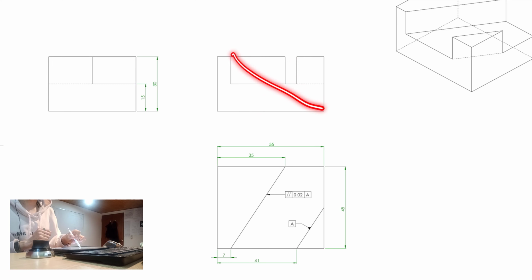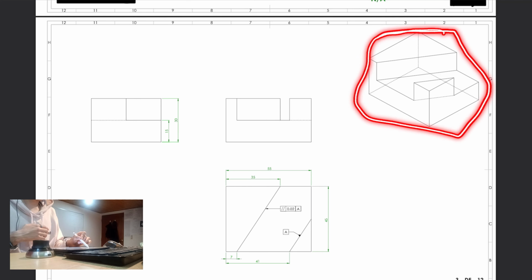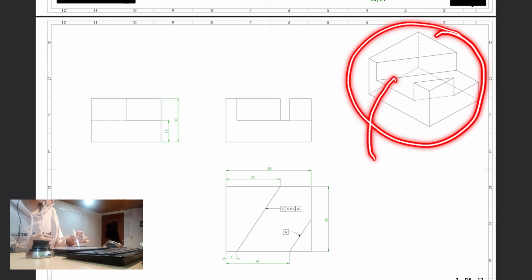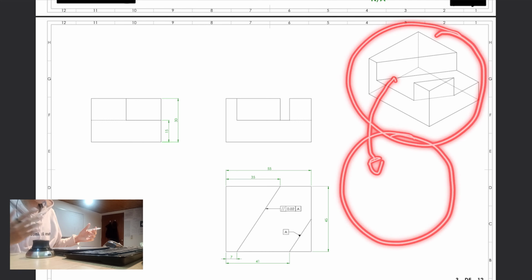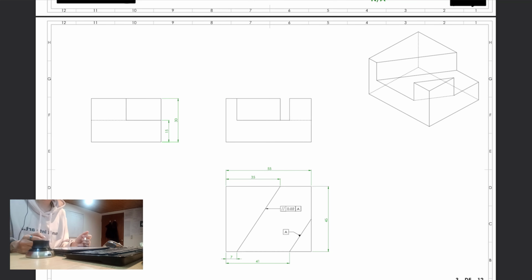Do not place information that is not required, because that is going to save space. And the next thing that I wanted to mention is that you have to keep the proportions. For example, I would place this, I don't know, around here. You have to eliminate the views that do not contain any information. This is a huge mistake, as I mentioned before.